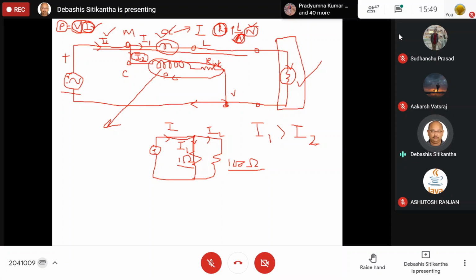Not only this, we also use a resistance known as internal resistance in series with it. When two resistors are connected in series, the equivalent resistance is additive, so it is also high. Naturally, this path for the voltage coil is going to be very resistive. So it is going to limit the flow of current through this parallel path so that almost all the current drawn by this load passes through the current coil.